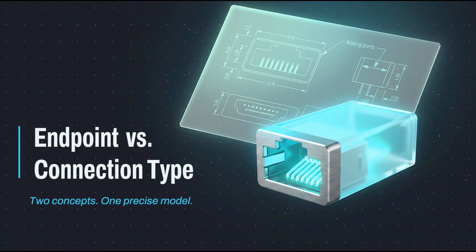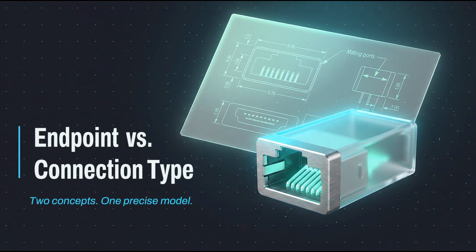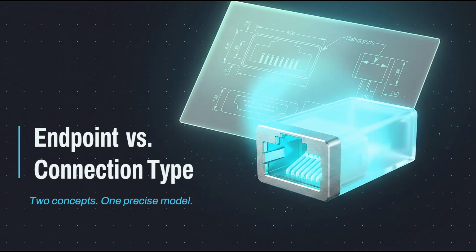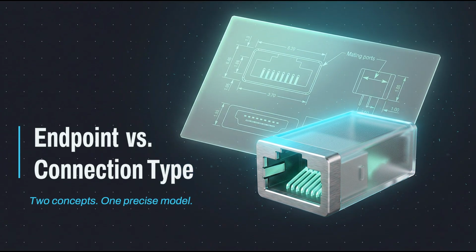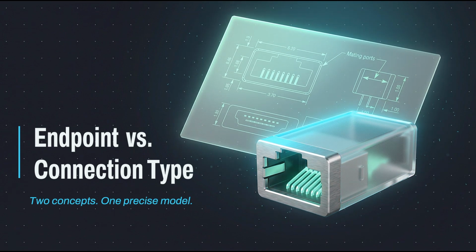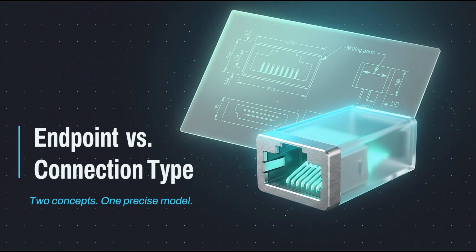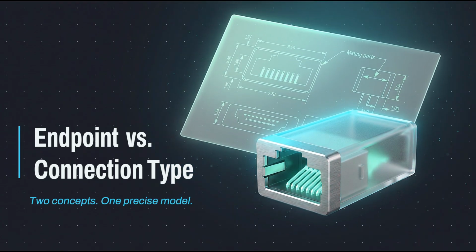You define a port def once. Then you use the conjugation operator, the tilde symbol, to mathematically flip the direction of the interaction features in that port. Features with direction in instantly become out, and vice versa. Features with direction in-out or no direction at all remain unchanged.